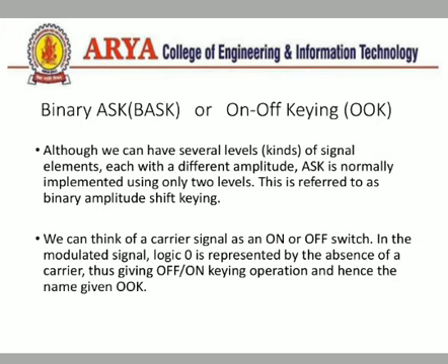Moving forward to discuss binary amplitude shift keying, which can also be named as on-off keying. ASK or on-off keying is the simplest digital modulation technique. In this method, there is only one unit energy carrier and it is switched on or off depending upon the message. Although we can have several levels of signal elements, each with different amplitude, ASK is normally implemented using only two levels.